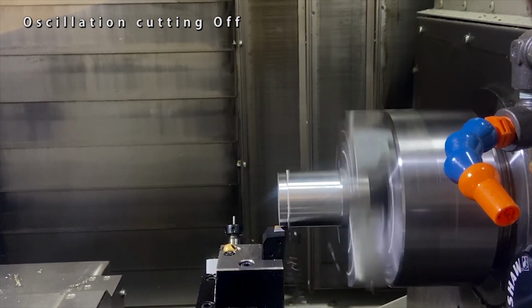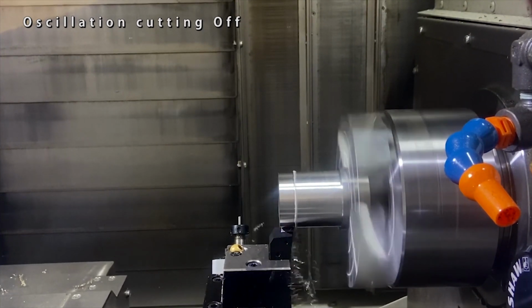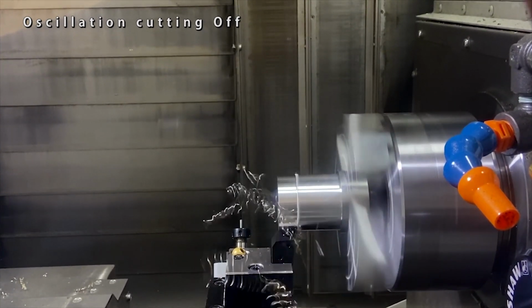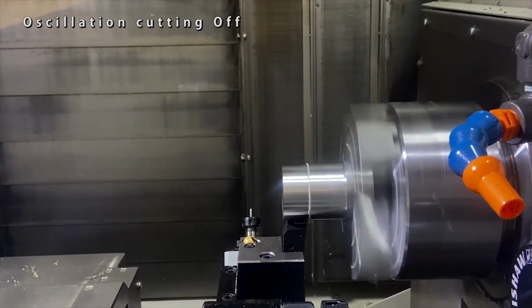Okay, this is OD roughing in the lower turret. At first, turning without oscillation. Without oscillation, you can see long cutting chips. This is not good for automation and the chip conveyor.